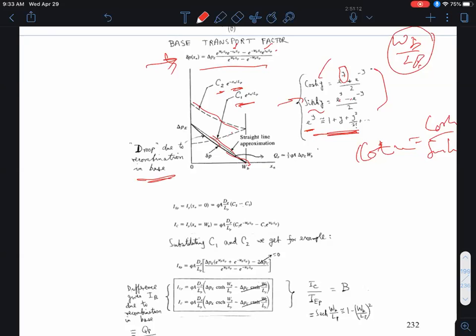All right. Now, once I get that distribution, I'm home free because I know how to calculate diffusion currents. What is the expression for a diffusion current? Well, let's look at JP diffusion, which is equal to dP/dx, that's a concentration gradient, times the diffusion coefficient DP, but with a minus sign because stuff flows from high to low concentration region. That gives you the hole particle flow per unit area. To get the current due to that, I have to multiply by the hole charge, which is plus Q, therefore the minus sign stays put. That gives me the current density JP. To get the total current, I have to multiply by the cross-sectional area of the diode.